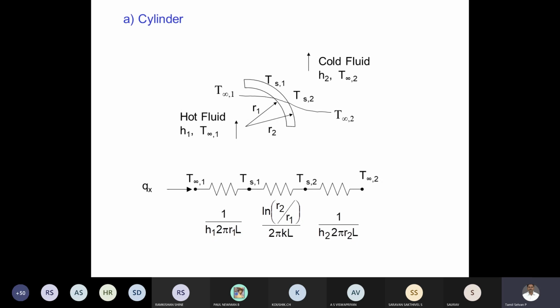That's why air cooling is not encouraged in multi-cylinder engines. We know that, right? IC engines have fins. We will be discussing fins in module 7, different types of fins: rectangular fin, triangular fin, circumferential fin, etc. Fins are used in electric motors as well as in single cylinder engines. The purpose is to dissipate the heat generated inside the engine cylinder to the surrounding fluid. But in multi-cylinder engines, in cars and buses, why don't they use it? Any idea?